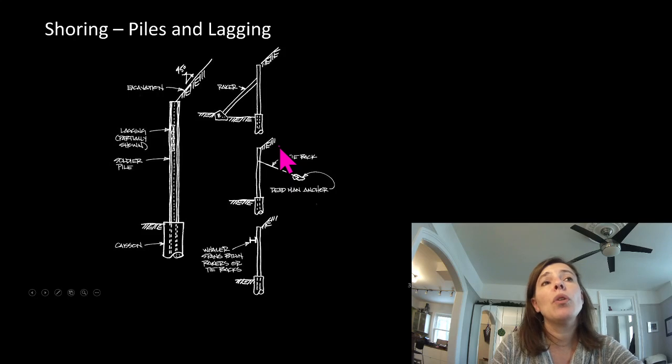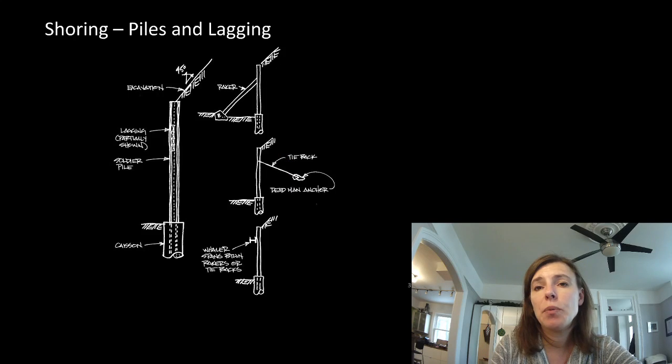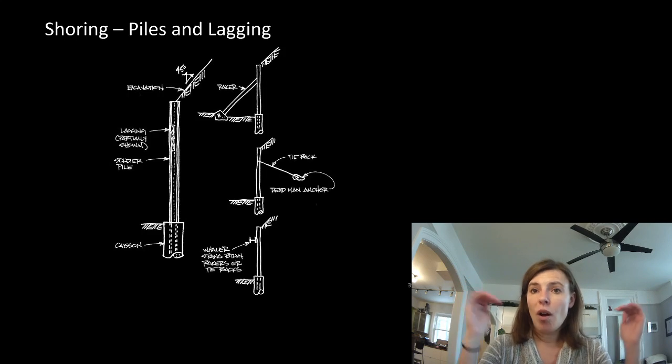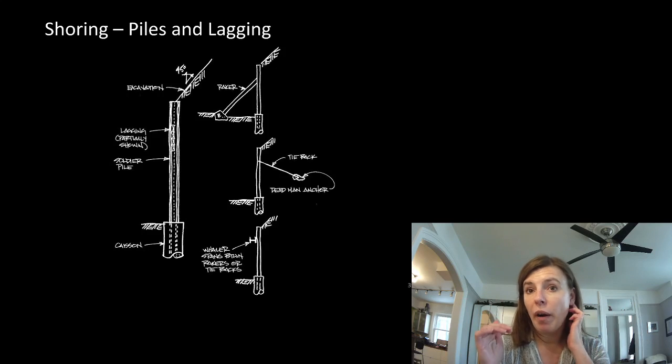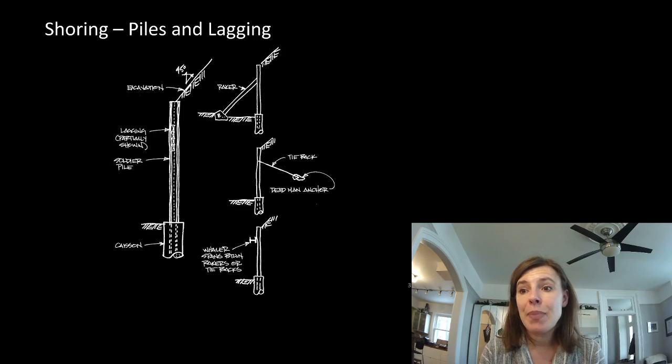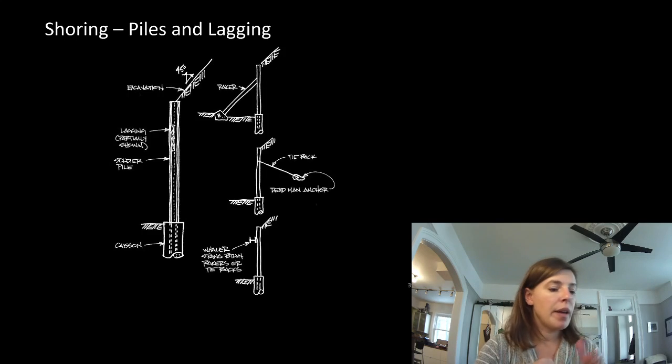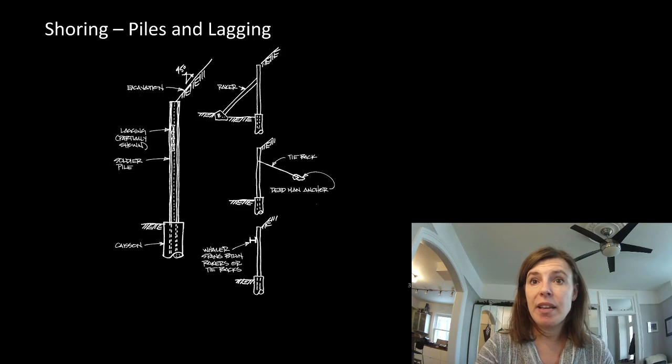Shoring. So shoring is what we do when we need to retain soil, but it's not the final structure. Where you might see that is when you need to retain soil that's not braced at the top by a floor temporarily. So if you're in a major city and you've been walking down the street, you know that you've stood on the sidewalk and been able to look into an 8-meter deep hole right beside you.